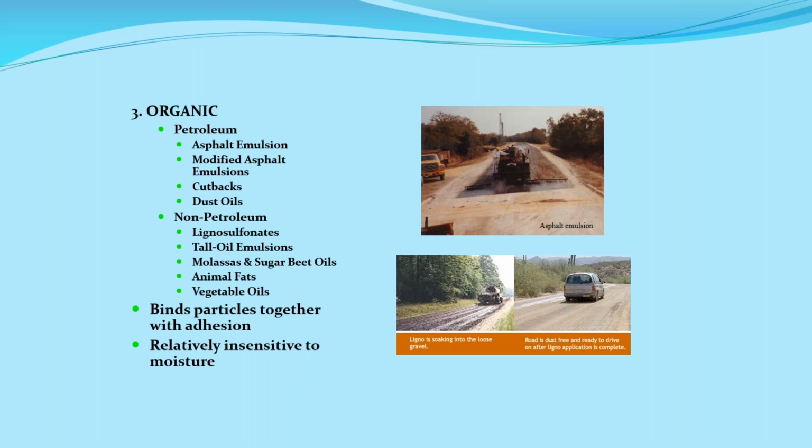Generally speaking, and this goes back to something I should have mentioned a little bit earlier on, before you do any type of stabilization, if you have some weak subgrade soils, or if you have a subgrade soil that has, say, a spring under it, an area where water comes up into it, you need to deal with that weak subgrade soil or that moisture before you ever think about stabilization.